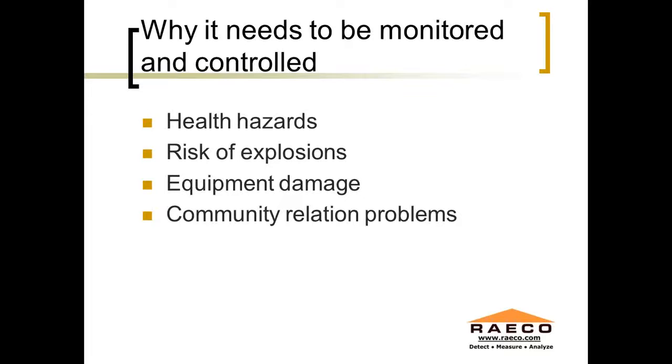Another big concern is risk of explosions, and that really is tied to combustible dust. Now what we're talking about today is a photometer. Photometers are not actually designed to pick up a concentration that would be indicative of combustible dust, but what a photometer-based measurement can do is indicate if you're not having proper cleaning practices in an area. As an example, if you look back, Imperial Sugar Plant was a major combustible dust explosion that took place, I believe, back in 2009.